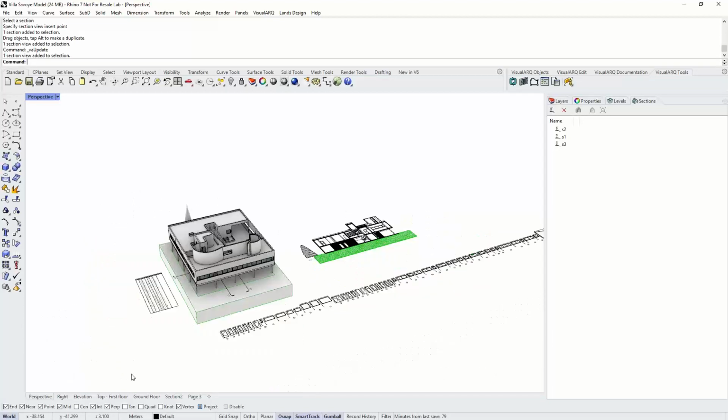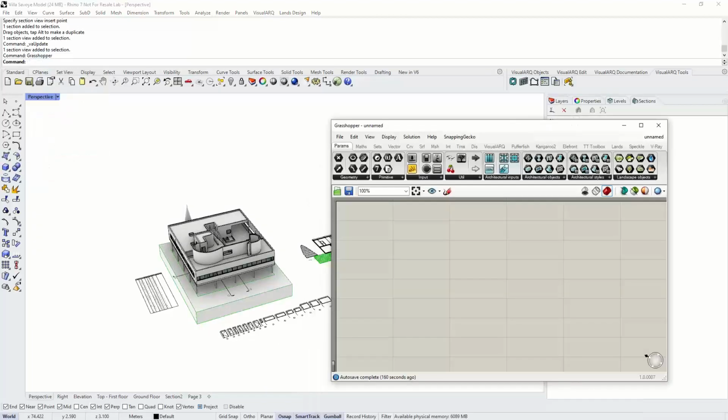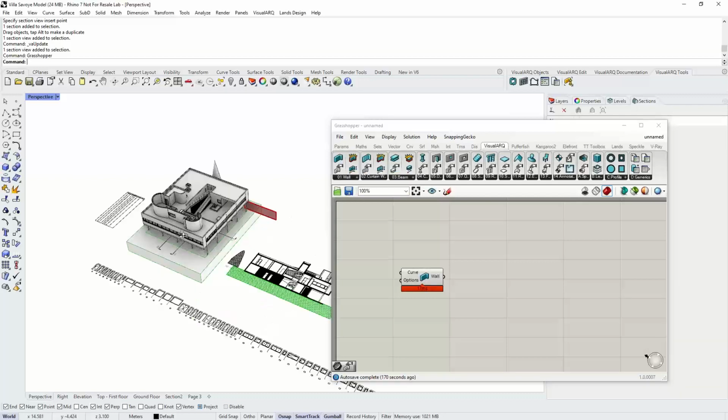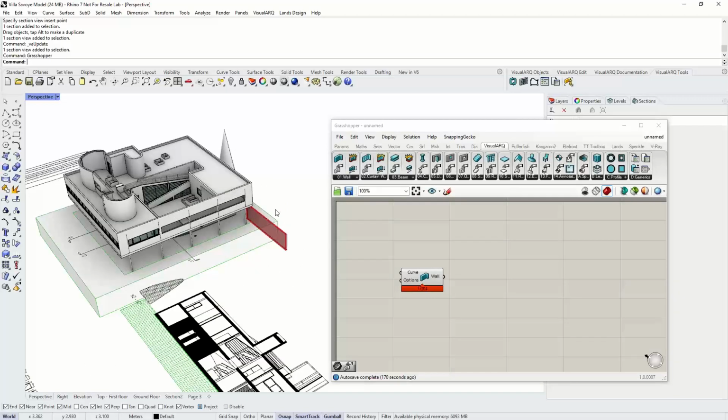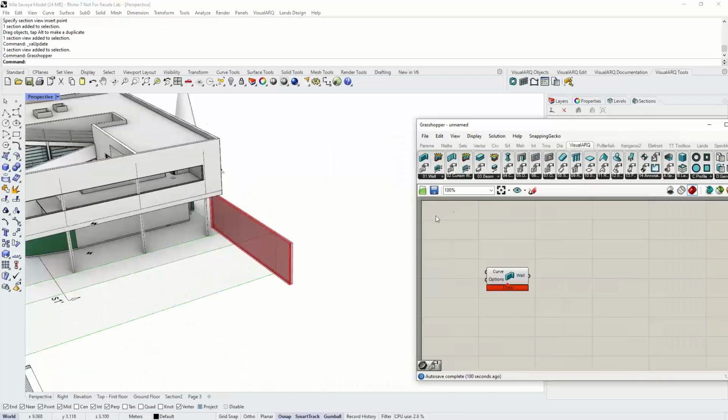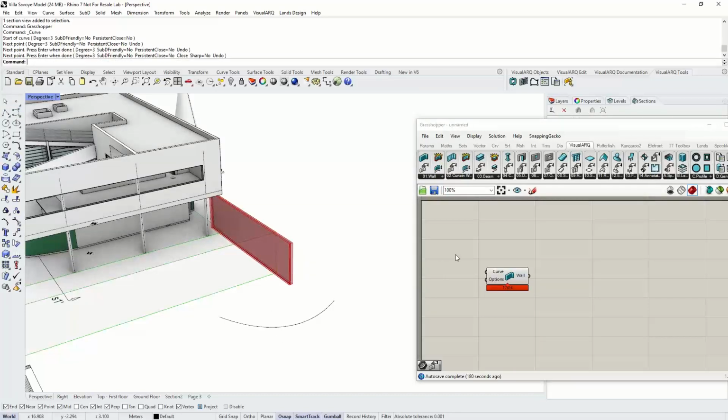Okay. Let's go back to Grasshopper as I wanted to show you. So here we can see all the visual objects to create new objects from zero. For example, in case of a wall, we just need to have a wall component. Okay, in this case, it will require a path curve that we can draw here. So we can reference this curve and connect it to the wall.